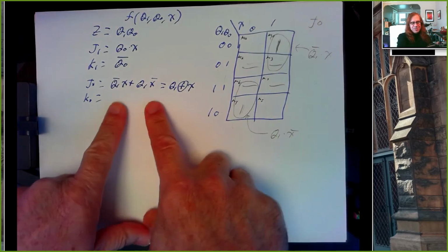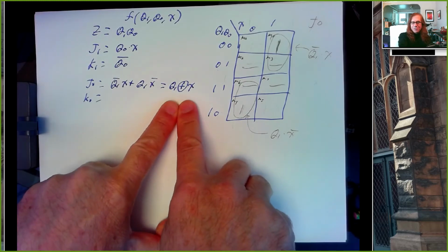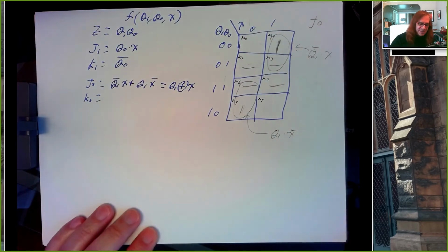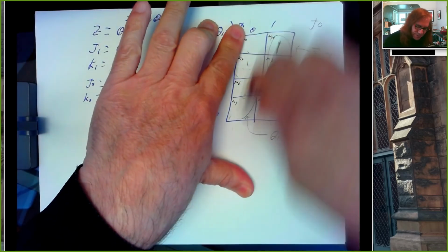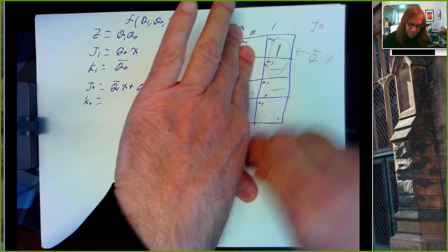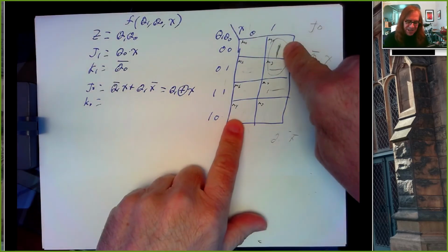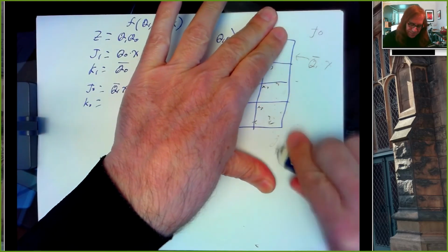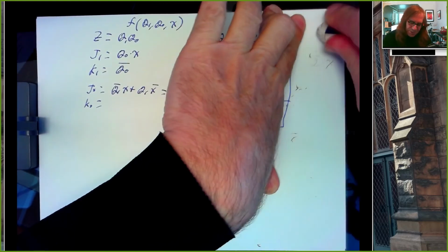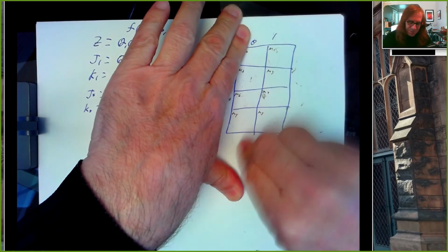So we could build this with a pair of AND gates and OR them together, but that's exactly the same thing as an XOR. So if you have an XOR in your box, you can do it like that. Make your circuit a little simpler. And the hint to think about XORs is when you've got diagonals going on, or checkerboards, play around with an XOR truth table, see if it looks like it might work for your equation.